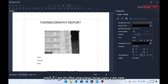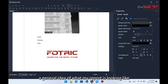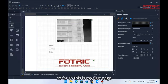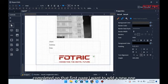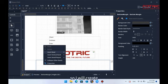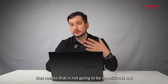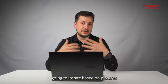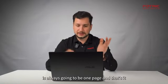And if I go to the preview, now you can see a general idea of what my report is looking like so far. So this is my first page. Now, having that completed on that first page, I want to add a new one. So I will create a new unbound detailed report section. That means that it's not going to be repetitive. It's not going to iterate based on pictures. It's always going to be one page and that's it.